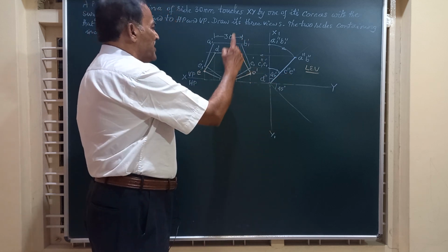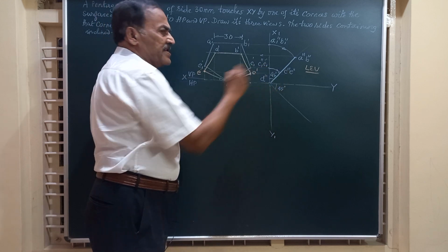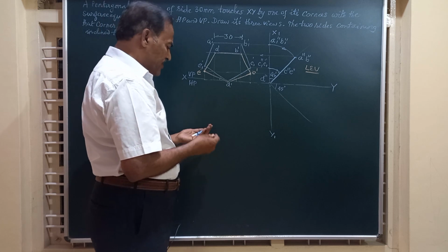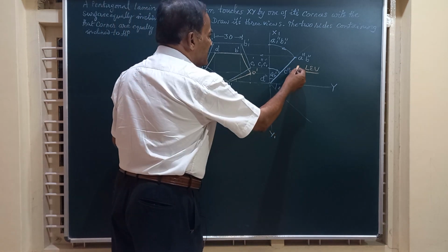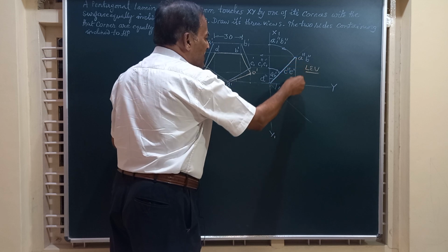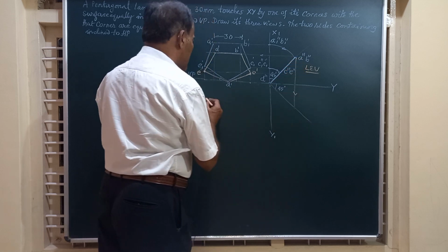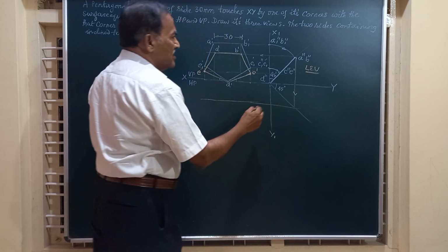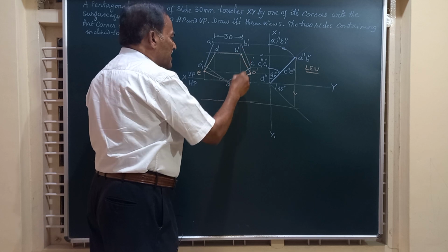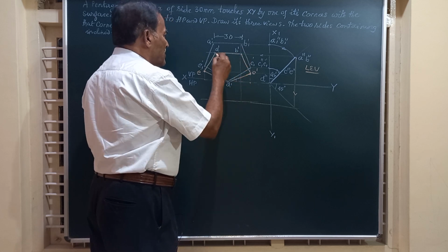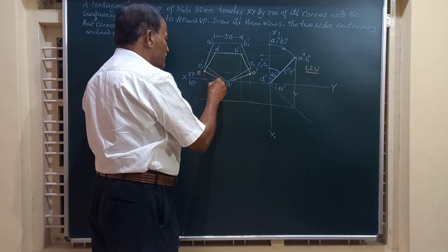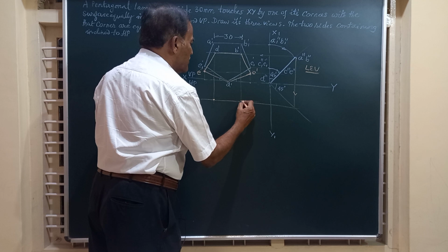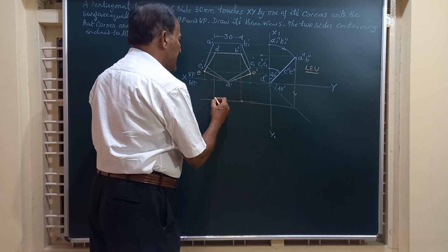Friends, we have got the final front view, we have got the final end view, and we need to obtain the final top view. So how to obtain, friends? Let us start from the point A. Write a vertical line from there till here. Draw a horizontal line from here. Then this is on A and B. Vertical line from A, vertical line from B. So these two points you are going to get here. So this point is going to be B dash and this is A dash.